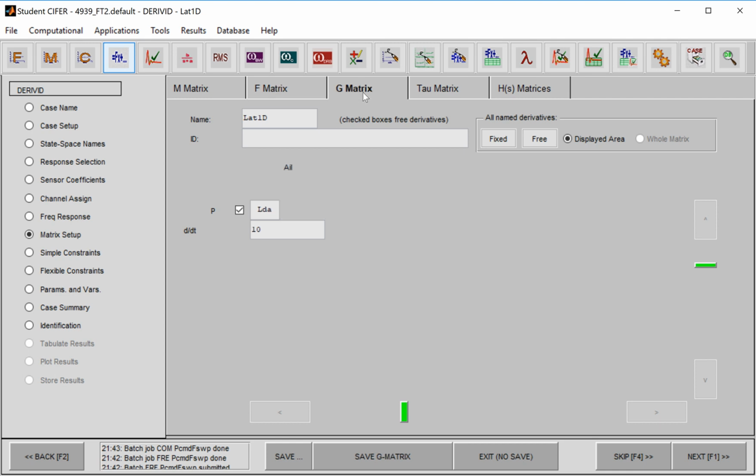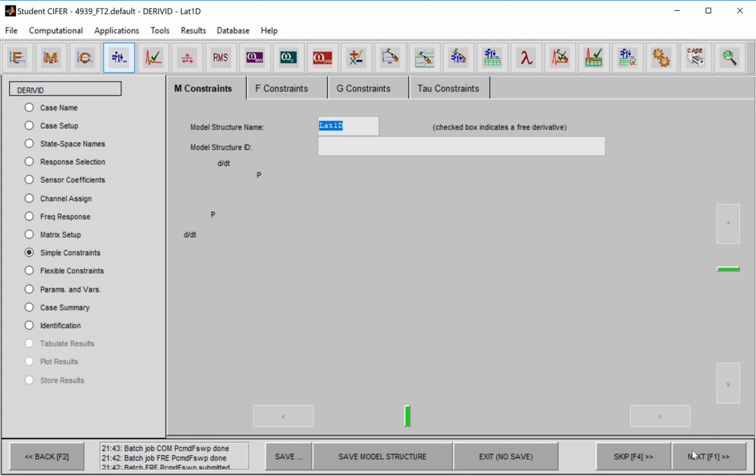It's really important to remember that you're getting multiple answers, or multiple estimates, for what should be a single actual answer. So the aircraft ultimately will have one LP and L delta A, and you should be able to compare them. If you want to compare notes with other students, you should have the same answers, because it's only one aircraft and we tested it at one airspeed.